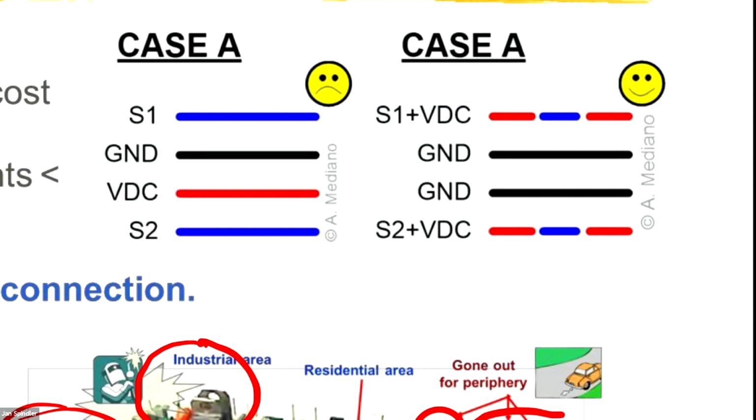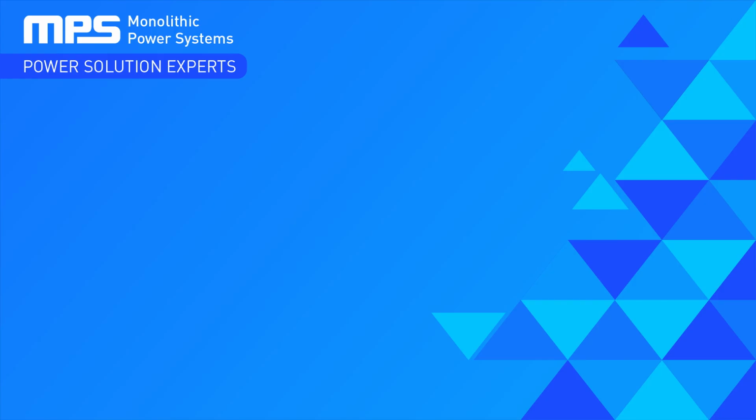The advantages of connecting VCC and GND in a normal PCB are not very big, because the distance between them is not very small. The only advantage of VCC and ground planes is to put one very close to the other. If they are not very close, you will not have that kind of decoupling effect through the full PCB. So in general, it's better this way. You have the possibility to have, for different signals, a good return path close to the signal. This is the idea.